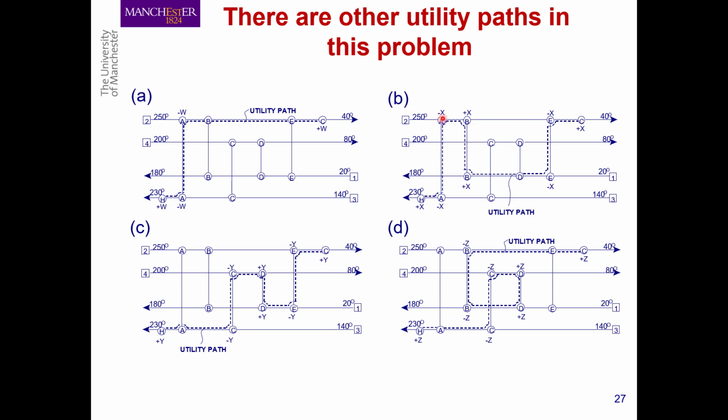And if you see that here again, the thing that we are trying here is to shift the load between different heat exchangers, and by shifting the load, we can actually play with the temperatures available, and we can change the size of these heat exchangers. Here, for example, in figure C, you have another path that is again going from hot utility to the cold utility. So if it is just connecting, for example, two units, we just call it a path. But if it is connecting a hot utility to the cold utility, we call it a utility path.